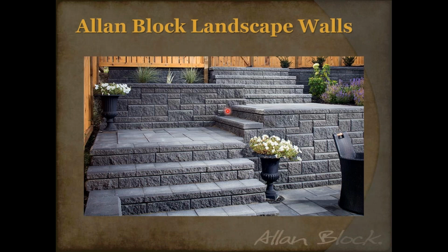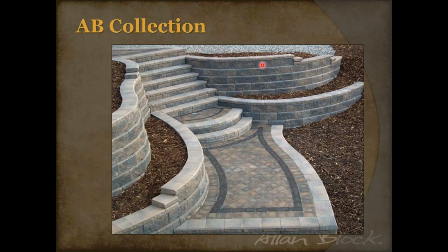On the flip side, here they did a little bit of both, right, to kind of create that flowing stair where they did 12-inch steps here, but then they did a little bit of a switchback to go parallel with the wall and then up the hillside again. Again, trying to make it work. You get into a set of steps like this where you're blending all your knowledge. Again, you've got right up the hillside because that's what the grades are showing, but then you can kind of make it a little more fluid as you work down the gradual hillside here.